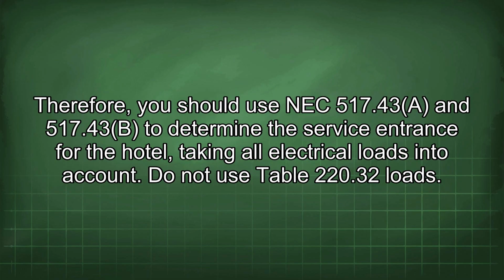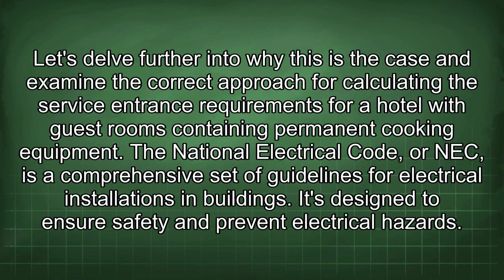Therefore, you should use NEC 517.43 and 517.43b to determine the service entrance for the hotel, taking all electrical loads into account. Do not use Table 220.32 loads. Let's delve further into why this is the case and examine the correct approach for calculating the service entrance requirements for a hotel with guest rooms containing permanent cooking equipment.